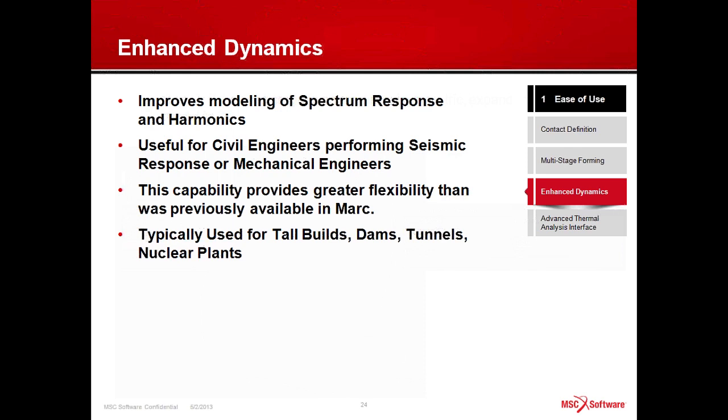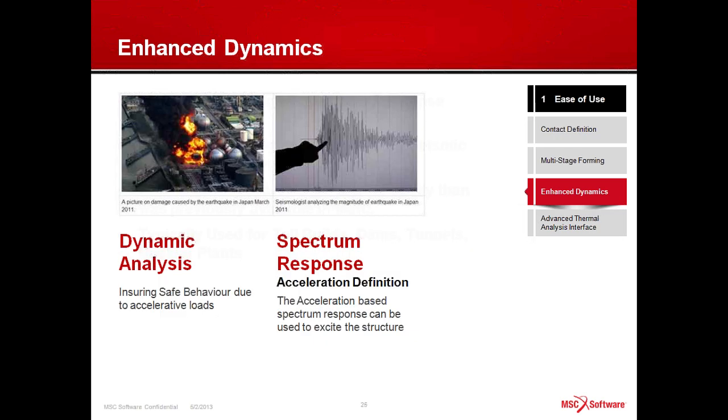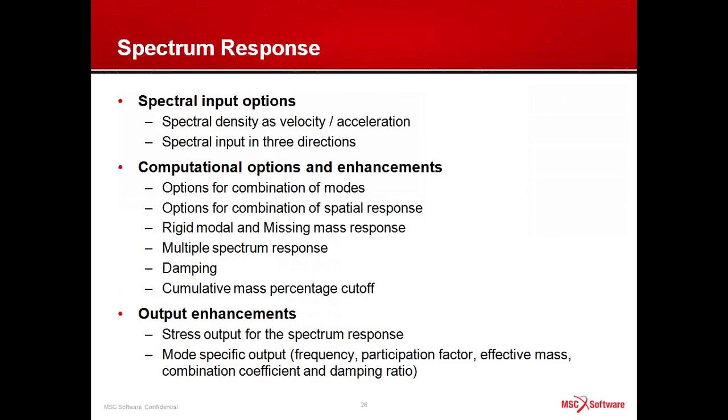Another general ease of use enhancement that we did was improving the dynamic capabilities in Marc. As everyone knows, over the last few years, we've had some significant dynamic events, earthquakes, other types of failures. Marc was not as sophisticated as other products, including our sister product, MSC Nastran. So we've put in more technology to deal with dynamic events and to deal with spectrum response calculations that are utilized in the civil engineering community and in other industries as well.